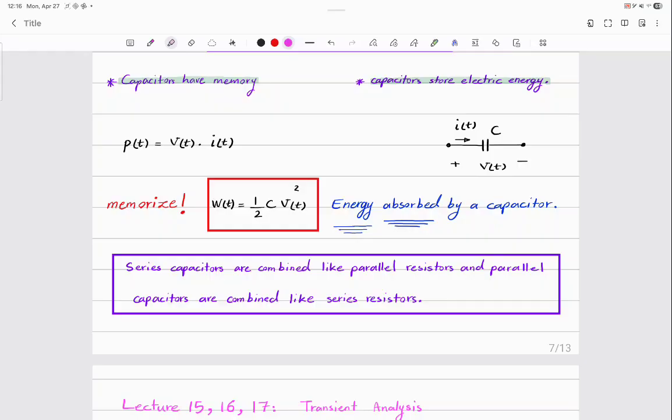The current of the inductor, definitely. No matter what the question is asking you, the current of the inductor or the voltage across the capacitor should be calculated. No matter what the question is asking. Can you tell me why? Because you need it for the next step.